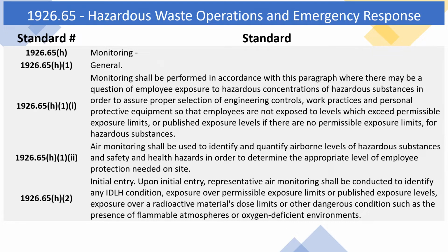1926.65 H2. Initial entry. Upon initial entry, representative air monitoring shall be conducted to identify any IDLH condition, exposure over permissible exposure limits or published exposure levels, exposure over a radioactive materials dose limits, or other dangerous condition such as the presence of flammable atmospheres or oxygen-deficient environments.